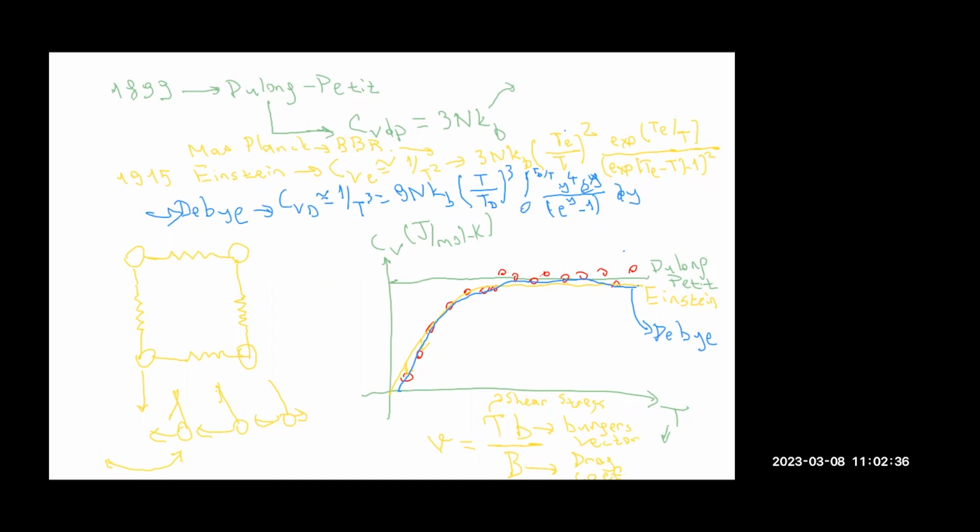And if you plot the speed of dislocation, in meters per second, against applied shear stress, in Pascal, you will activate the dislocation right away. Even at 1 megapascal, you have dislocation activity for edge dislocation. So they are linearly correlated with each other.